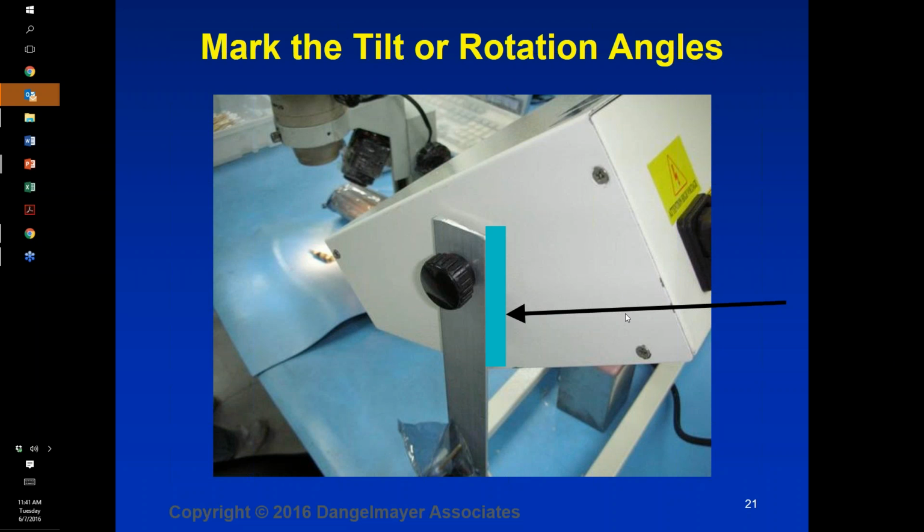The reason that we have humidity specifications, and typically we find them in military applications, is that when the documents that the military used were written, 20 years ago, 30 years ago, quite frankly, the ESD control materials we had at that time didn't work very well at low humidities. But that has changed dramatically over the years, and you'll find that most of our ESD control materials, at least the high quality ones, are rated for humidities down as low as 10 to 12%. So it really isn't a requirement to have high humidity in an ESD control program, and ionizers in this ESD control program will make sure that whatever charges are generated on the insulators or isolated conductors are very rapidly removed.